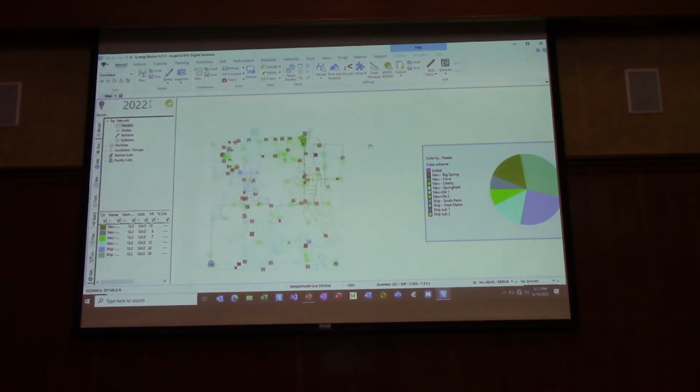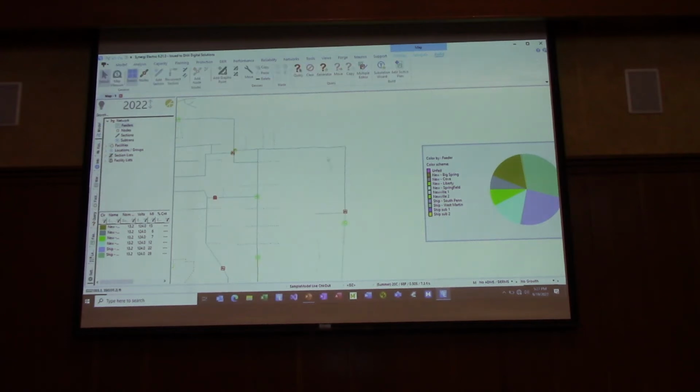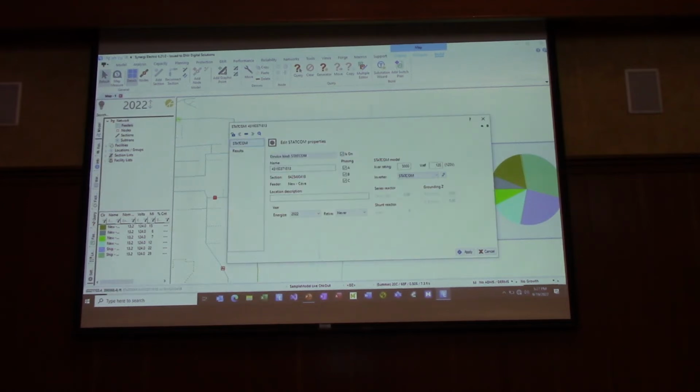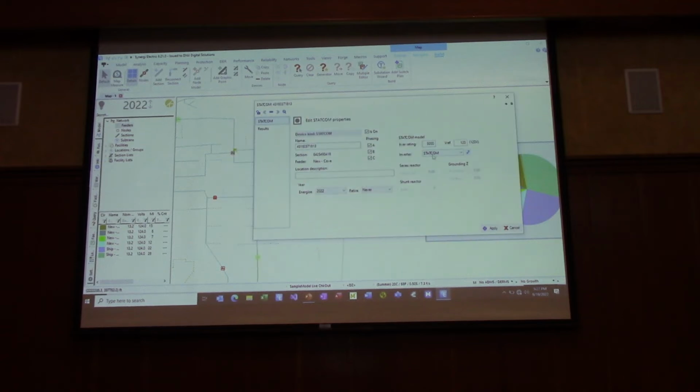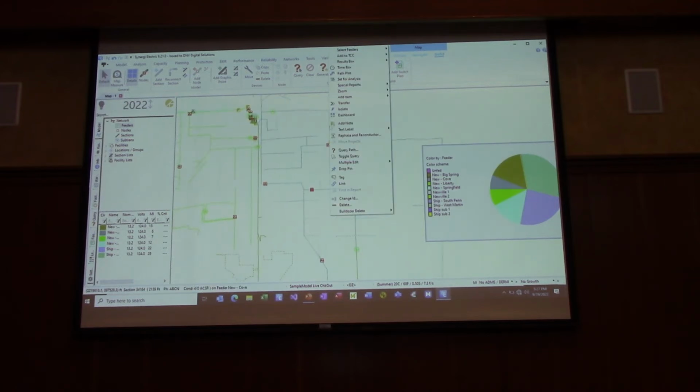Okay, so let's look at this application here. Now, I've got a StatCom sitting down here, and I'm going to go to the build tab. I'm going to stick it up on this feeder. Probably not a lot of you have modeled these in Synergi. It's pretty straightforward. You set your inverter up, and you have a size. This is a 5 MVA StatCom. I'm going to run this on one feeder here.